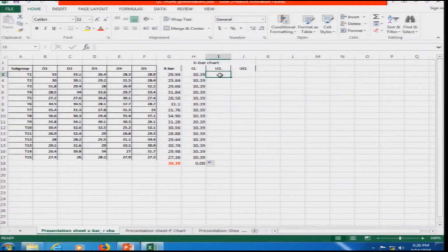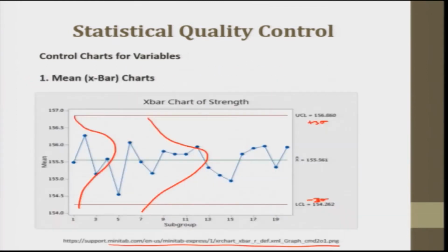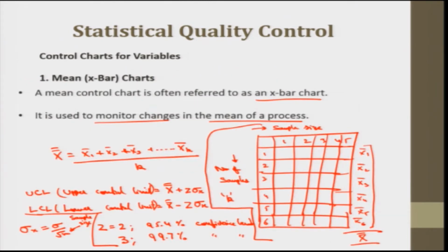To pick the lower control limit, I can calculate the sigma value. Another way is I can use the values given in the table that I discussed, okay. So, in this case I would like to put another formula, that is a quick formula for the x bar chart. The upper control limit and lower control limit can be calculated using the constants which were tabulated.